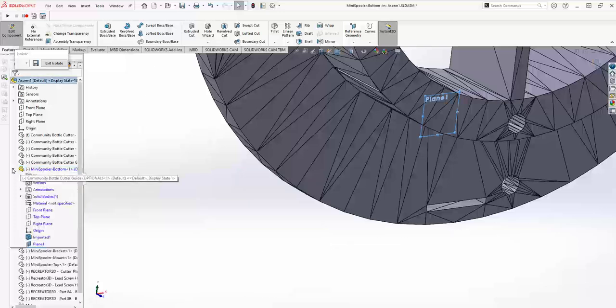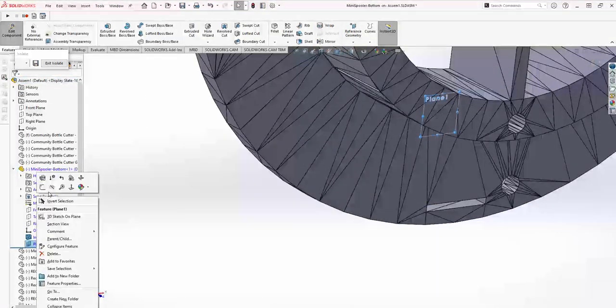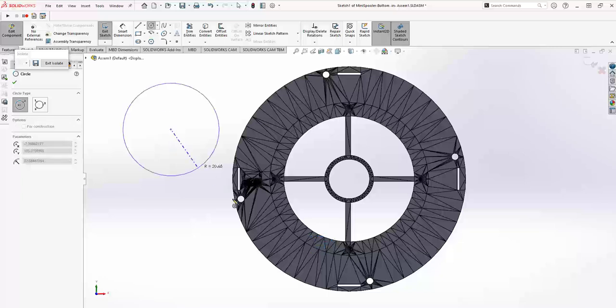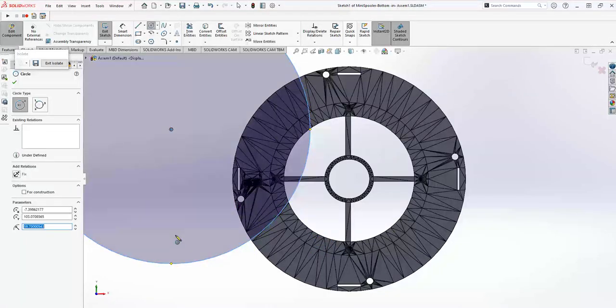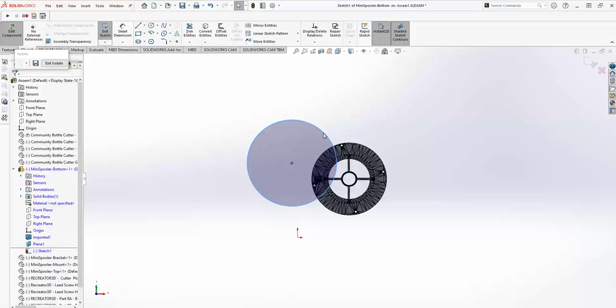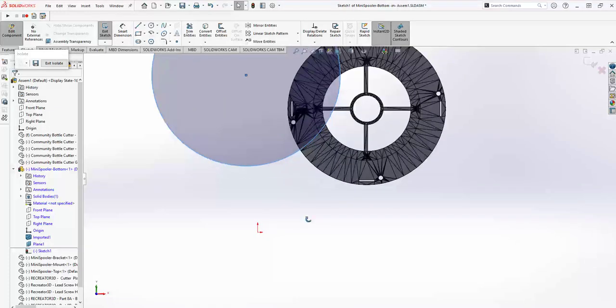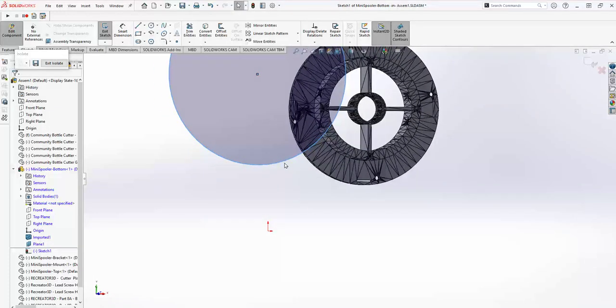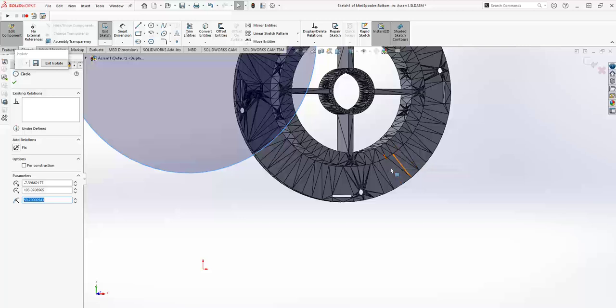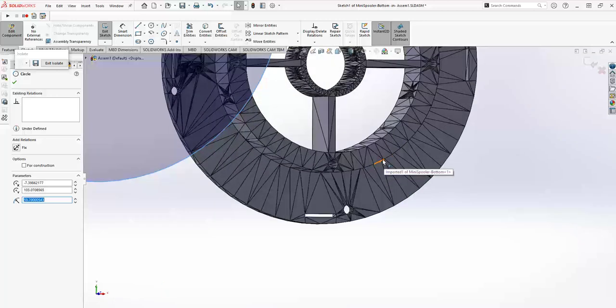All right, so now on that plane, you create a sketch, and in that sketch, again, make a freehand circle. So this circle doesn't have any condition. Make sure you didn't accidentally add a condition to that. So now I want that periphery to coincide with holding the shift and picking one point here.